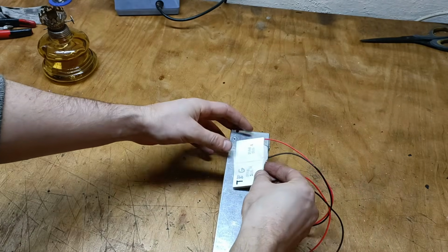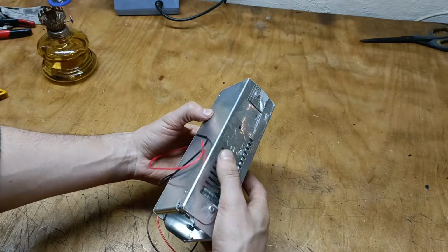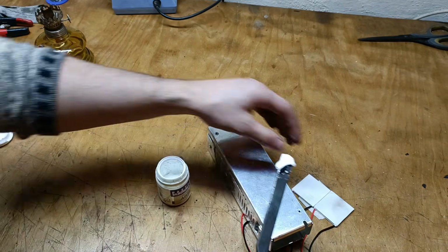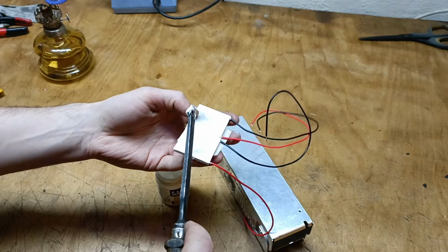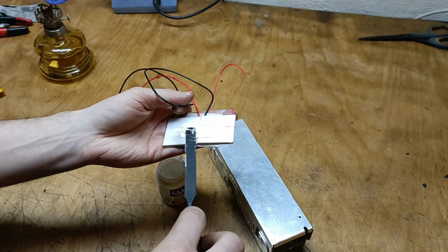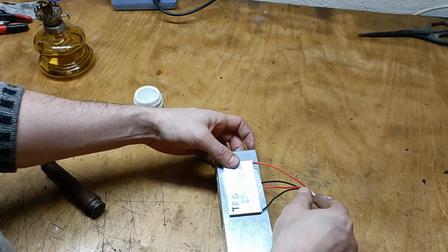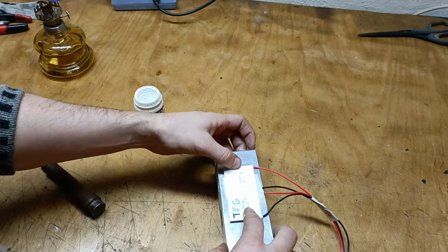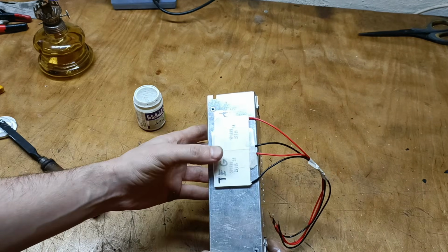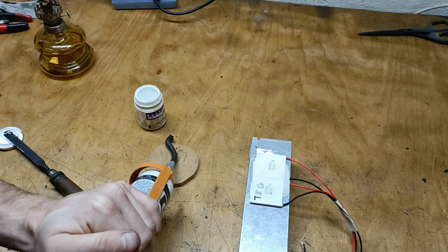Next, I placed the Peltier cells on the support structure, 2 cells on each side, for a total of 8 cells. Before gluing the cells to the structure, I applied thermal paste. Heat transfer is key in this project. We want as much heat from the lamp's flame to be transferred to the cells as possible, which will reduce kerosene consumption, of course. At the same time, we also want as much heat to be transferred from the cells as possible, but more on that in a moment.